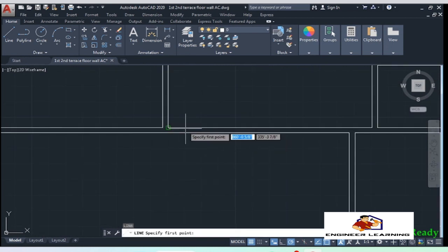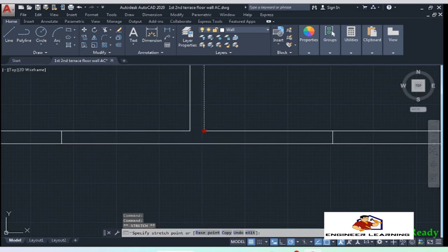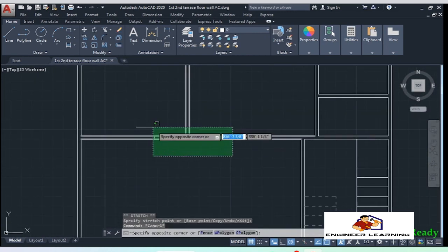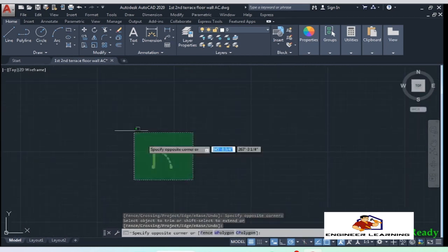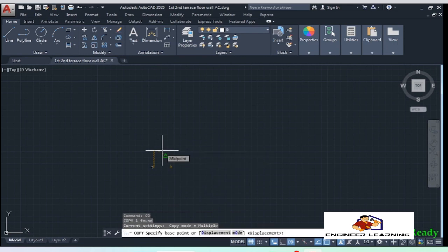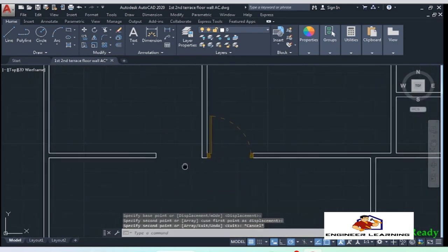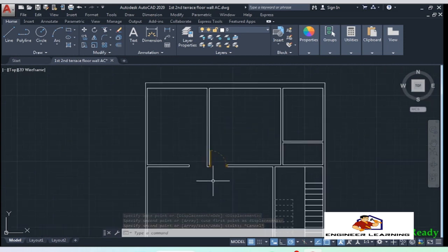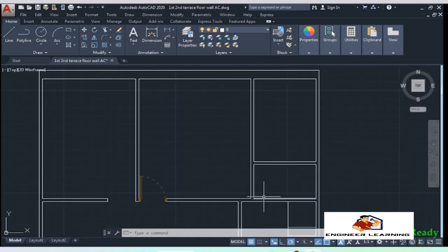With the help of the line tool, place a line at 3 feet from the wall like this for both the rooms. Now extend these lines to the edge. Trim to make the door opening. Copy the door with the CO command. Pick it with its pick point and place it up here. The thumb rule is that the door should be placed in such a way that it opens inside a room and leans against a wall like this. The only exception to this is when it is opening into a small size dressing room or bathroom.